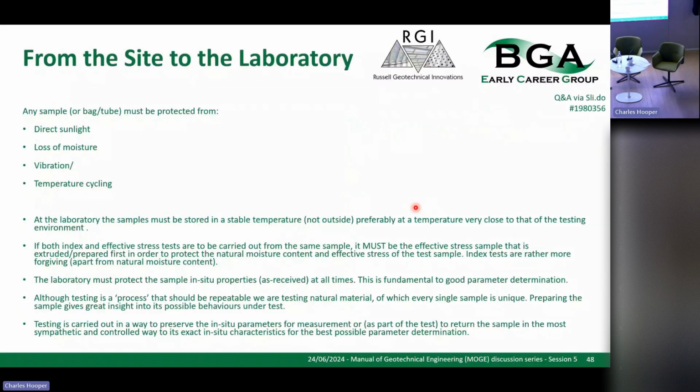So, from site to the laboratory, looking after the samples as they are taken from the ground. Rotary core samples would have to be immediately removed from their mylar tubes, the drilling fluid taken off them, and preferably they should then be mildly shaved, say 2 to 4 millimeters off the complete diameter of the sample to remove any influence of drill fluid.